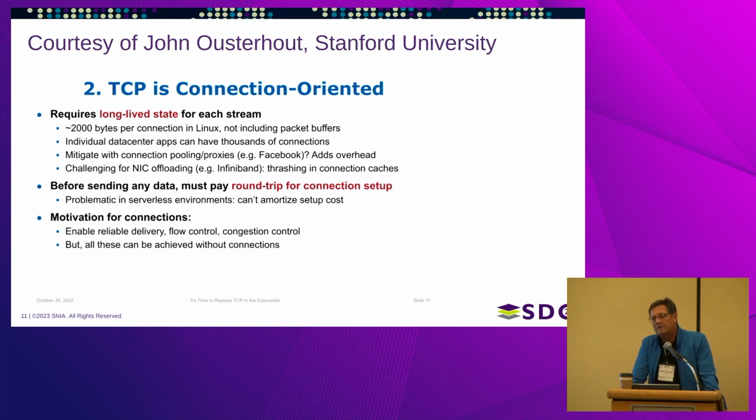What makes this hard, keeping this state persistent, is if you start offloading TCP in a NIC, particularly an FPGA-based NIC, you got to keep all those connections alive. And one of the most precious resources that we have in these FPGA-based smart NICs is memory, right? DRAM is rather slow compared to the line rate of processing in an FPGA. Embedded block RAM is a very scarce resource. We still count it in megabits, not in gigabytes, okay?